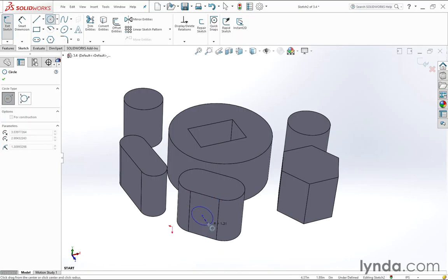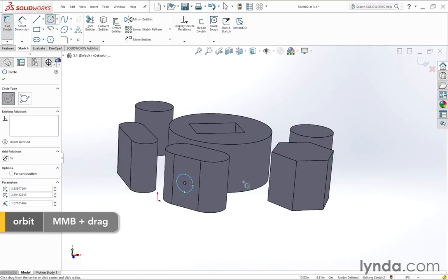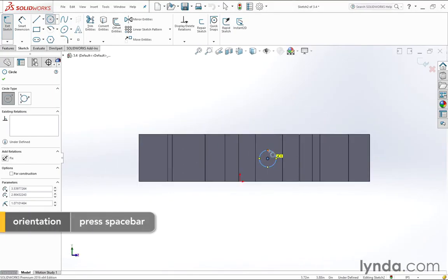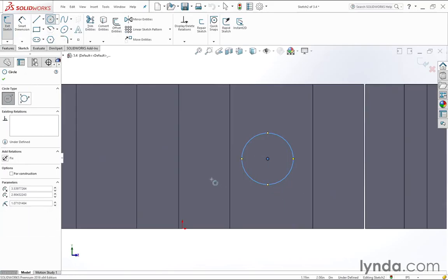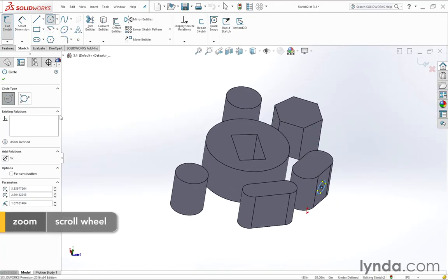I'm going to draw in 3D here, so I'm looking at the view in 3D. I'm not drawing in 3D. Or I can click on the space bar and I can click on this one here called normal to, which then I'll look directly at that shape. Once you have the shape, you can add dimensions if you want. You can tie it into the origin if you want. You can do a lot of things, but in this case, we're just learning about the extruded cut feature. So I'm just going to leave it as is.